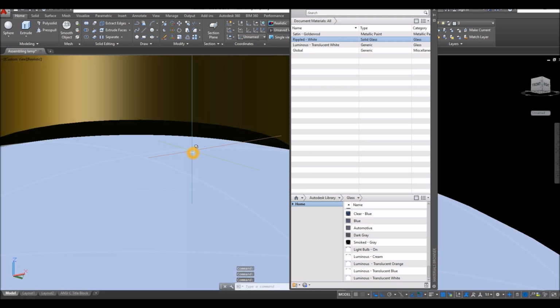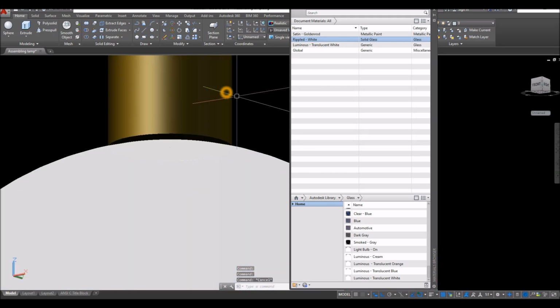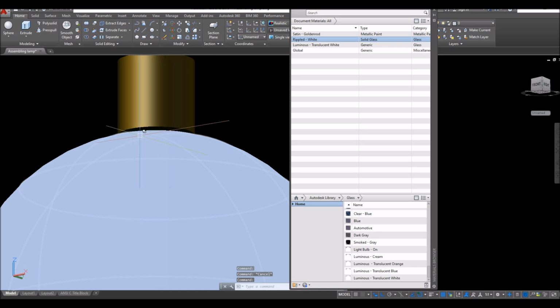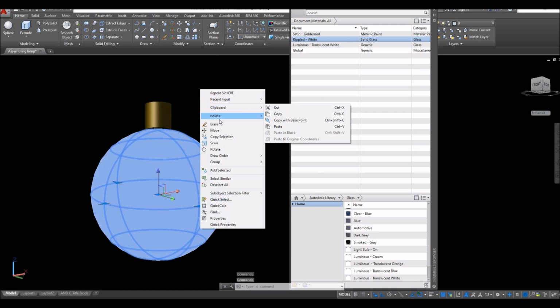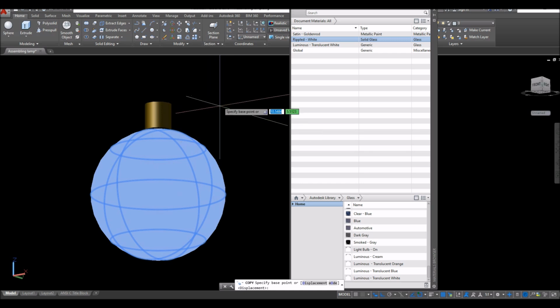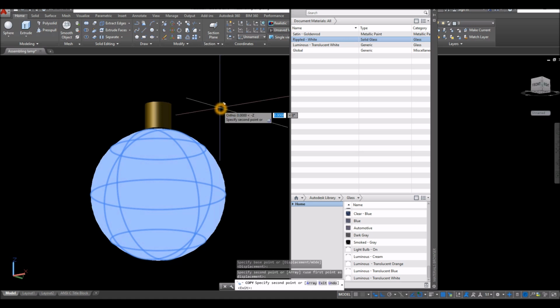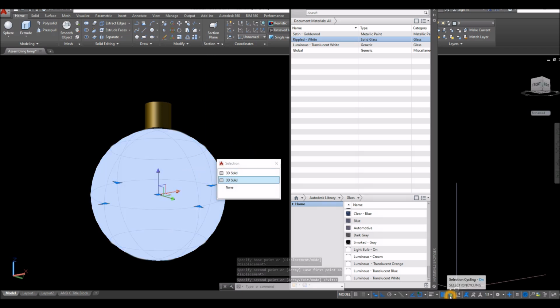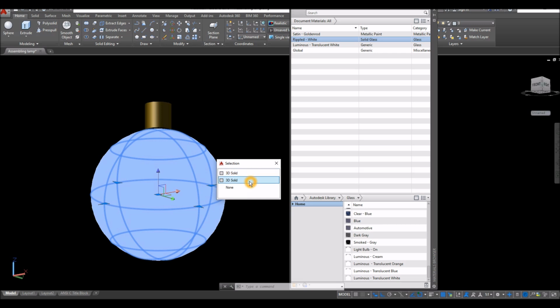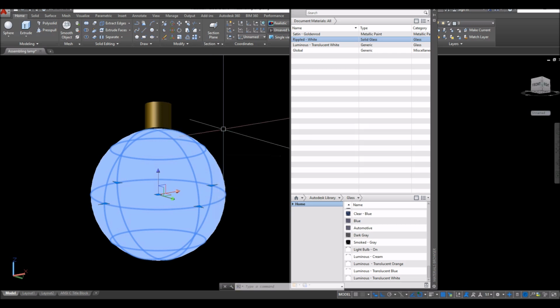As you can see here, this is supposed to be all the way down and curve at the tip. So what I'm gonna do is use this one as an object to subtract, to create a curve here. So copy selection, specify this point. You can use any point as long as you click on the same point for the second copy and enter. If you click this one, you can see the selection here. If it's on the selection cycling, you can see two 3D solid objects.